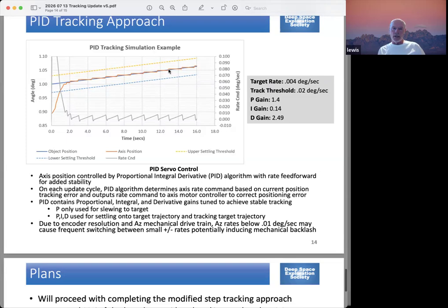And so basically the P and I and D are gain factors that tune how sensitive it is to those errors. In general, the larger the gain, the more responsive it is to that error. And so when you go out and field this thing, there's a certain amount of tuning that has to be done to adjust those parameters to make it work smoothly.